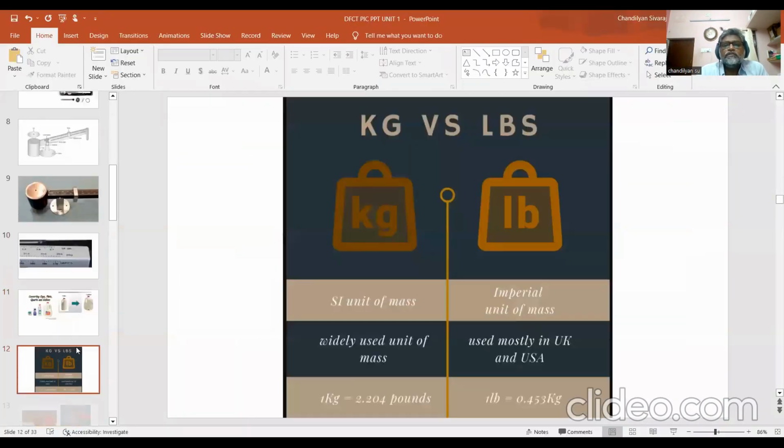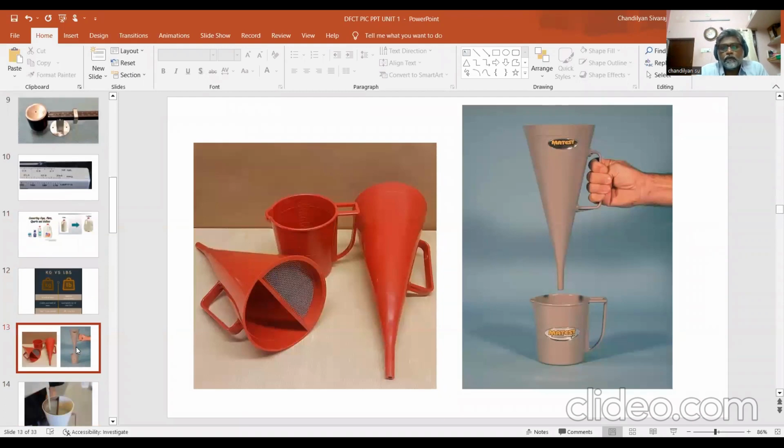This is what is called a Marsh funnel. It looks like a funnel, a standardized, calibrated funnel with specific dimensions, built exclusively for the oil and gas industry, especially for drilling fluid and cementing operations. Next semester, when you come to the laboratory, we will do this experiment by preparing the drilling fluid and measuring the viscosity. So this is called the Marsh funnel.